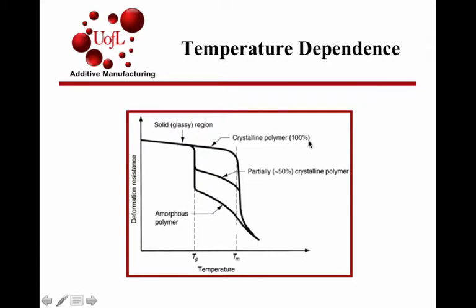Polymers that are semi-crystalline will have two transitions. One, they will go through this glassy region and then go through a rubbery phase and then melt completely at a higher temperature. The variations of these Tgs and Tms according to the structure allow a way in which you can change the processability as well as the mechanical properties and hence the design capabilities of the product.